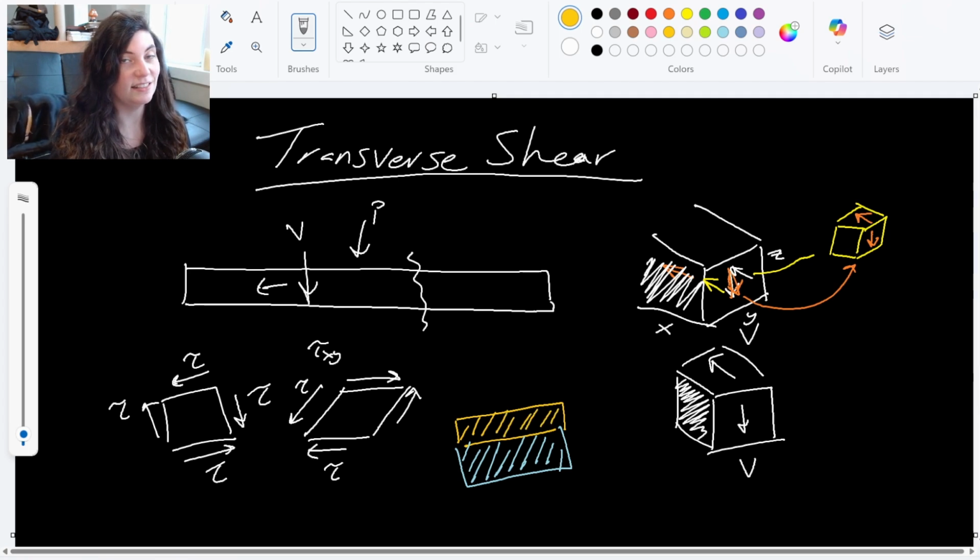is because this introduces a new point of failure, right? If I have a stress along this connection line, right where those two composites are glued together, that is now a source of weakness. It's a weak point for our beam, and our stress could be too high and our glue could fail. So we could have failures now, not only because of the bending moment, but because of this shear stress going through the beam.